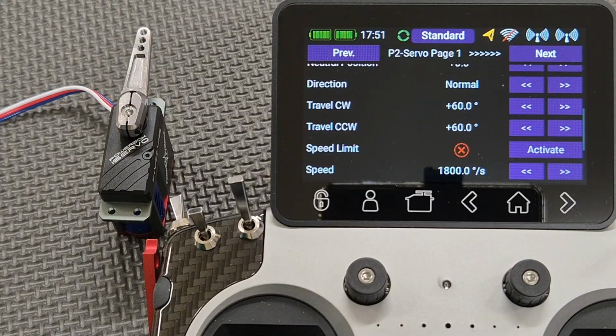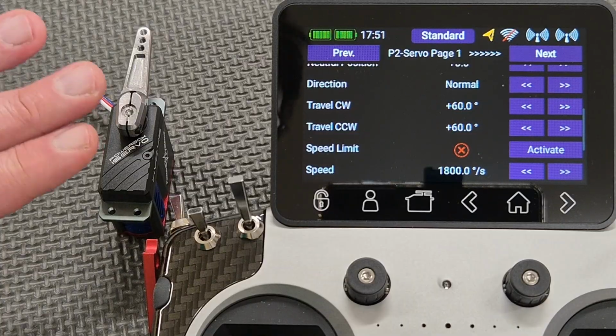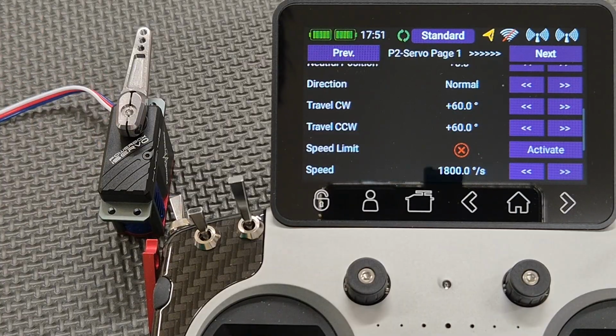So for those of you who are not aware, most serial devices like servos on S-bus, even the P2 bus, you need to be able to save the failsafe to the device. For instance, if you're running PWM, the receiver stores the failsafe data and feeds that out via the PWM port. But it can't do that with the P2 bus and serial bus systems, because they don't work in a similar way.